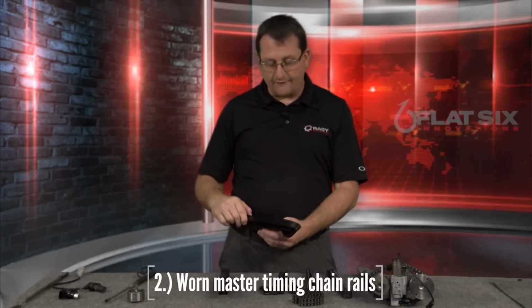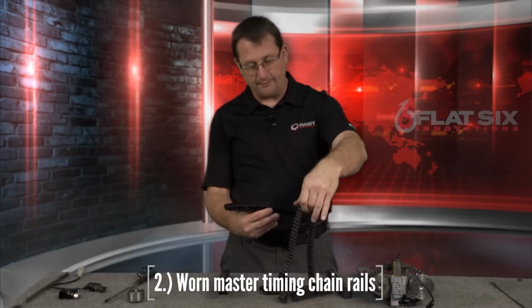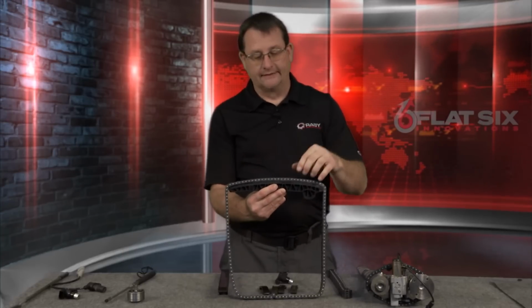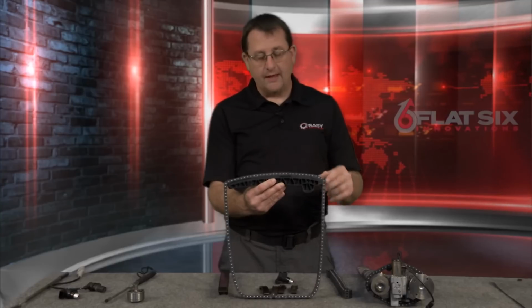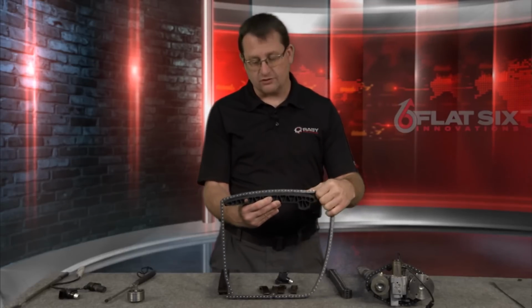Second, you may have your main master timing chain rails starting to wear. Now again, let's keep in mind what these do. These are pretty much the same on the 5-chain and the 3-chain, a little bit different physical design of them because one is made to support the chain differently than the other, but they still play the same role. These have a little bit of play as far as wear goes in the engine, and they play into this just a little bit. So let's say you got a little bit of wear from the IMS bearing, a little bit of wear from these chain rails, you're getting more of a camshaft deviation, okay?